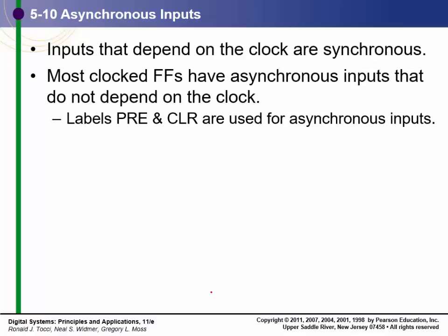You can have, and almost all clocked flip-flops do have, some asynchronous inputs. The two that are normally found are the preset and the clear. Those are used to set and clear the flip-flops at power up, or in the case of a latch, in order to